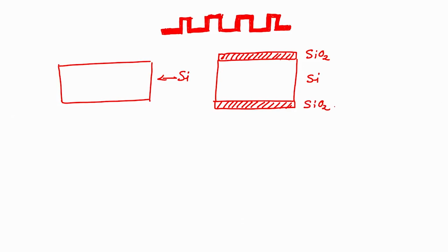Now, I want to have a pattern of photoresist which looks like this, right. So, what will be the next step? Next step would be I will deposit, or I will spin coat, the photoresist on the oxidized silicon substrate, right. That will be my third step.